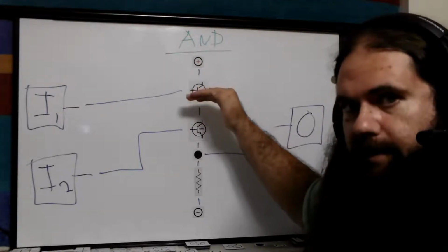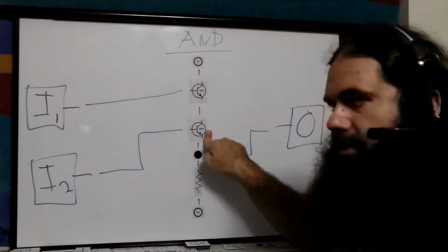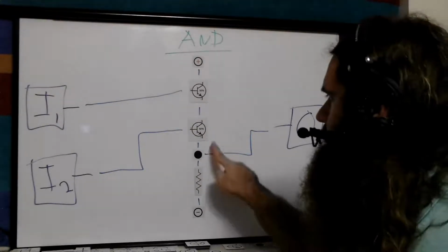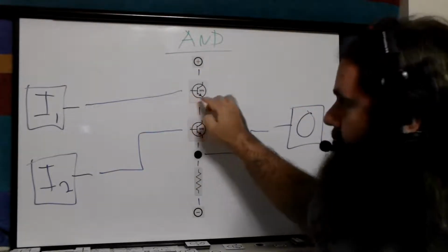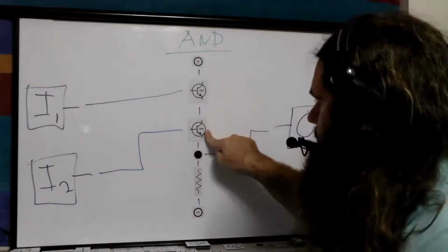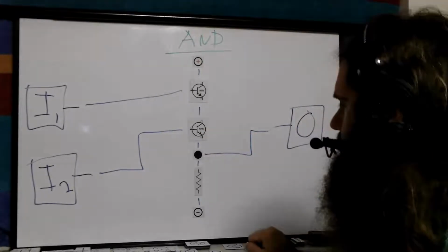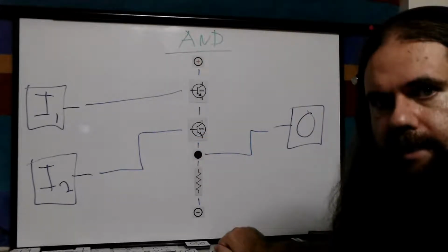Collector is, we haven't established yet. We're still working our way up. So this is conducting, but what is it conducting? The ground sneaks through. So I got about 0.2 here, but this is low. So this is not forward biased, so it's not conducting. So this is not connected to power. It's not going through. So that's empty, and you're getting low again.